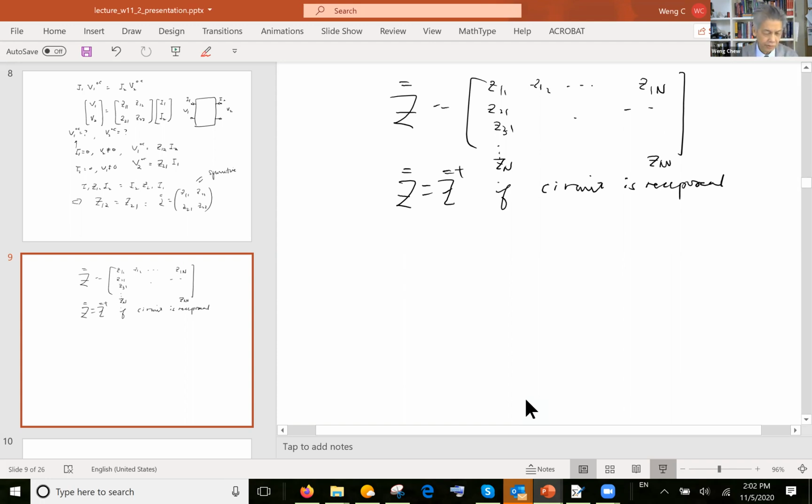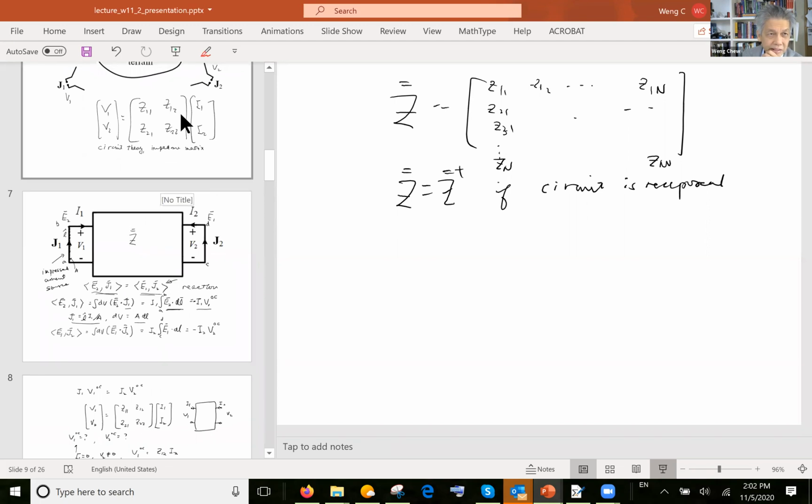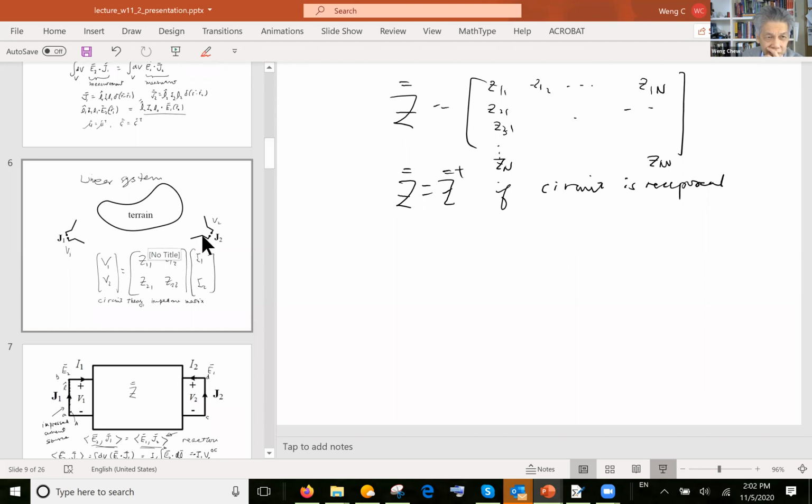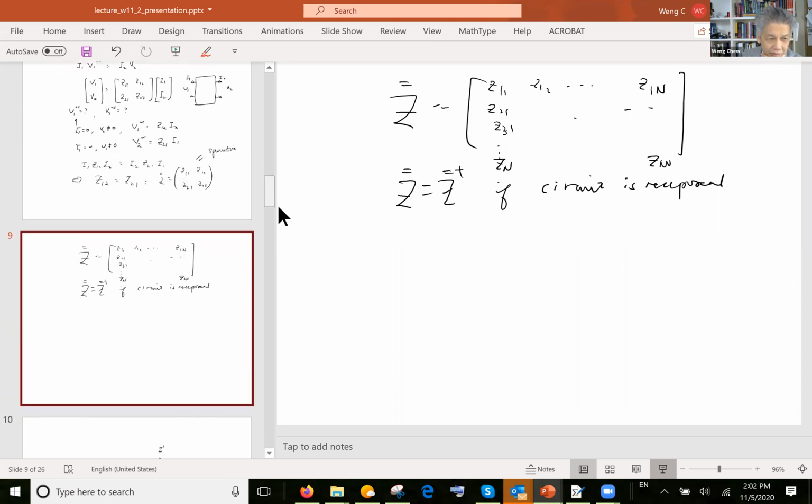So if there are no questions about this, what this says is that if you design an antenna system between the transmitter and the receiver, they are cross-coupled with this Z12 and Z21. If you transmit a wave from antenna 1 and antenna 2 receives it, it also means the other way around. That is, if this is acting as a transmitter, this is acting like a receiver, because Z12 and Z21 are equal to each other. If something transmits a wave between the two antennas, they also receive a wave between the two, is what it means. It's like a tit for tat kind of relationship.